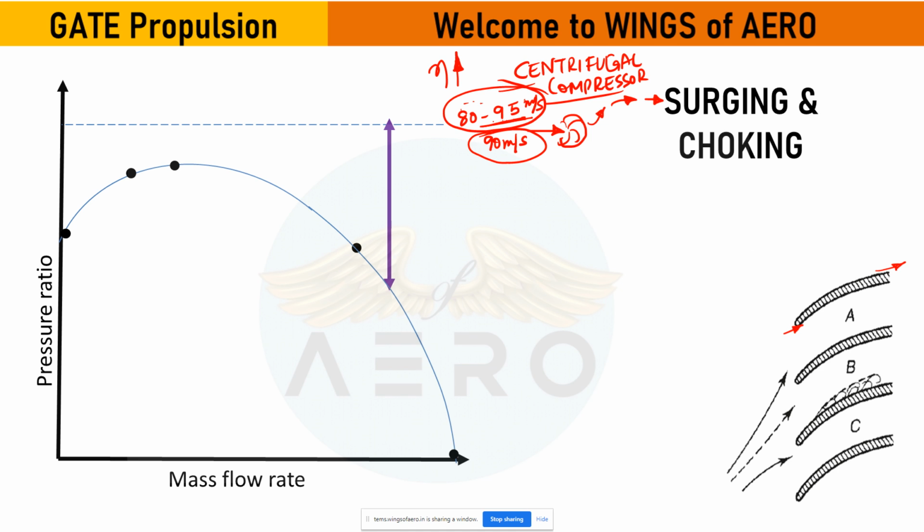It is the diffuser outlet velocity, because it is moving to the combustion chamber. Now if I increase the speed to more than 100 and beyond, what will happen to this blade? It will start to cause a pressure gradient because of reverse flow, or I can say it will lead to stall formation or turbulence, right?